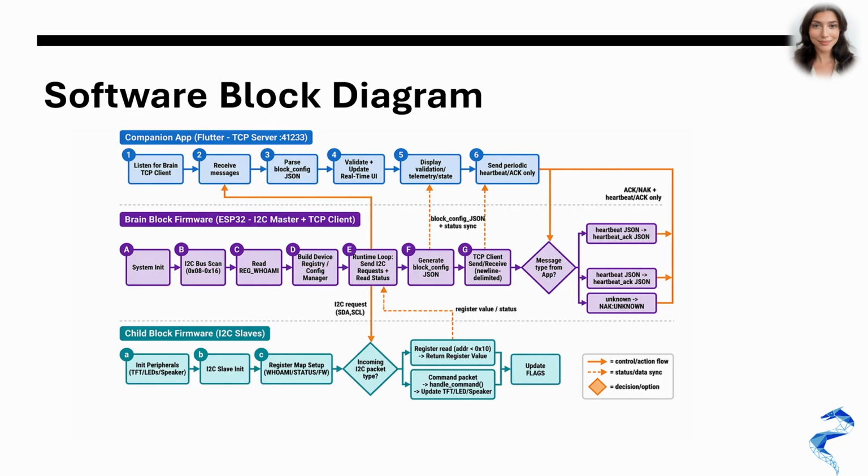It initializes, scans the I2C bus, reads whoami registers, builds a device registry, then loops by requesting status from child blocks, generating updated block config JSON, and exchanging newline-delimited messages with the app. It also handles app messages like heartbeat and unknown cases.